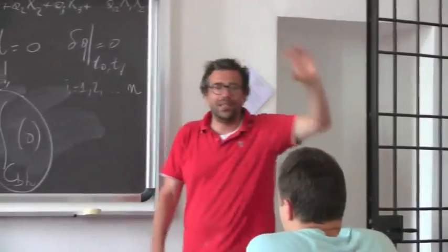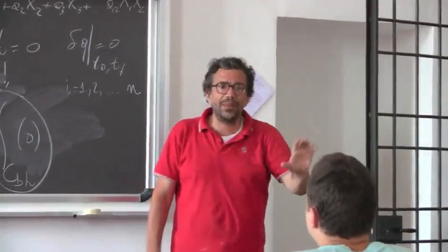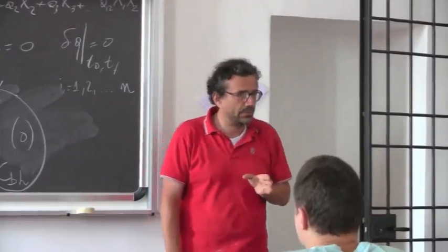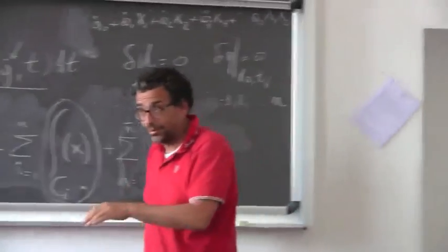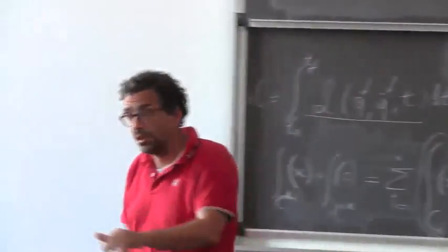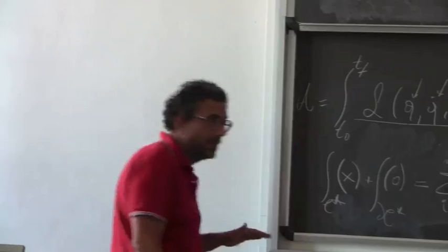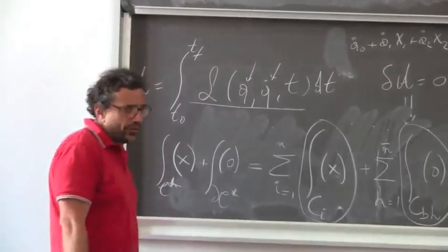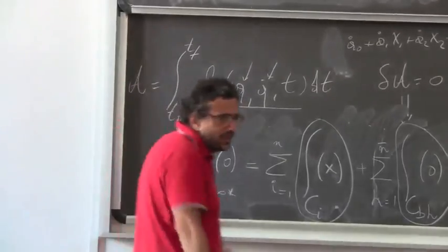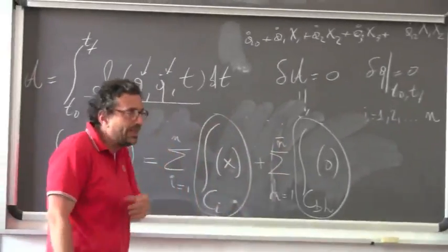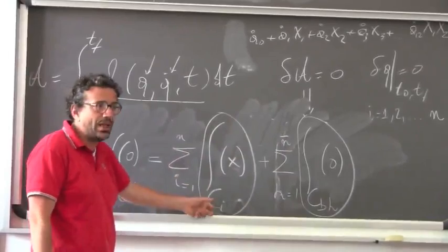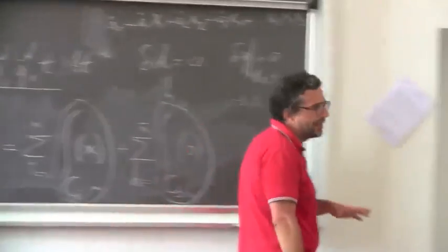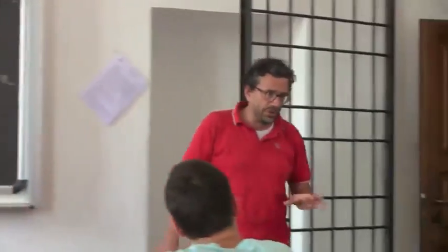There are many finite elements. Each finite element is suitable for a specific application. But the general procedure is always the same. You take this polynomial. There is no reason for having polynomials; you could have another function. The important thing is that you manage to calculate these integrals. In general, finite elements are expressed in terms of polynomials.